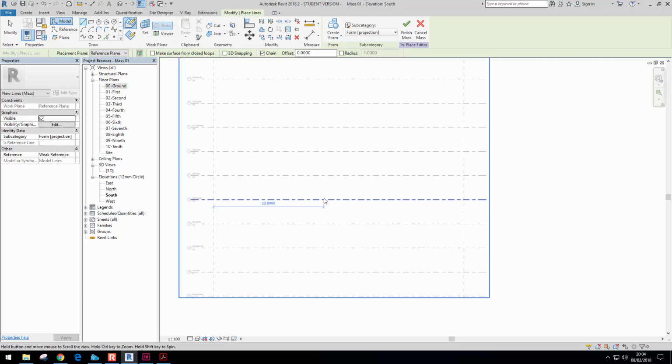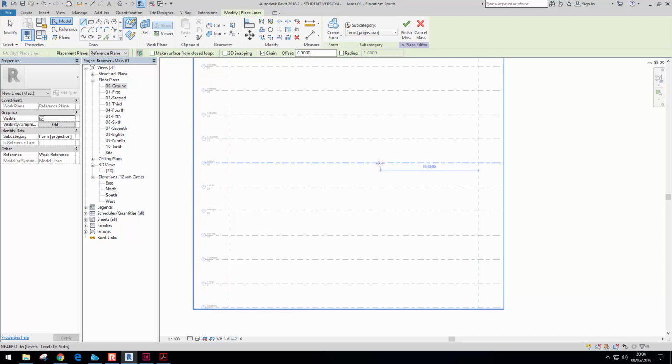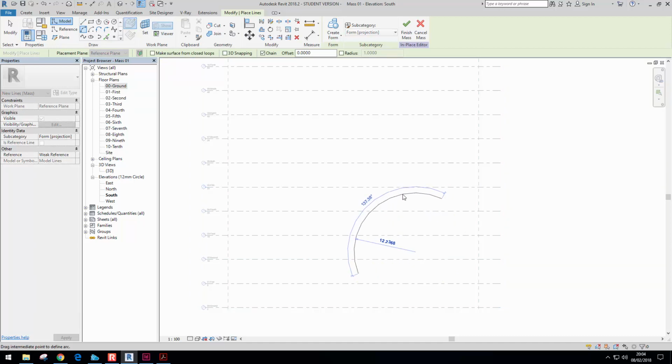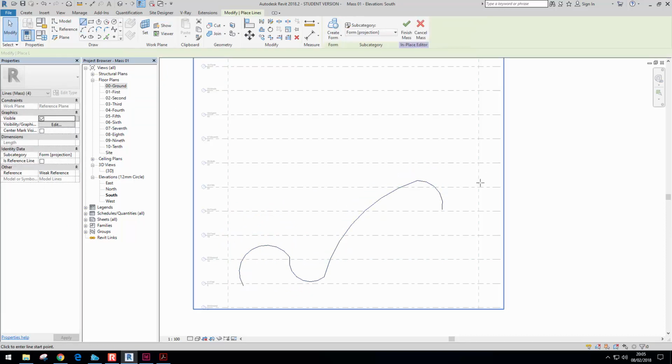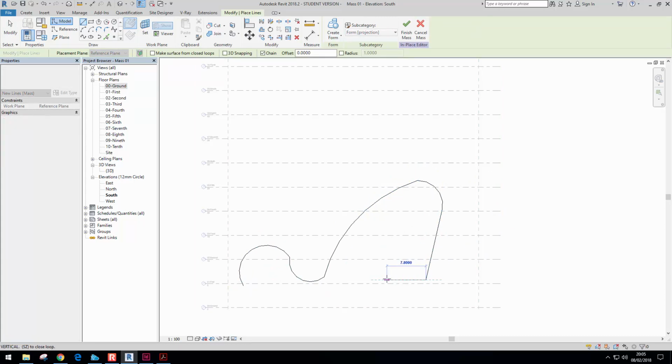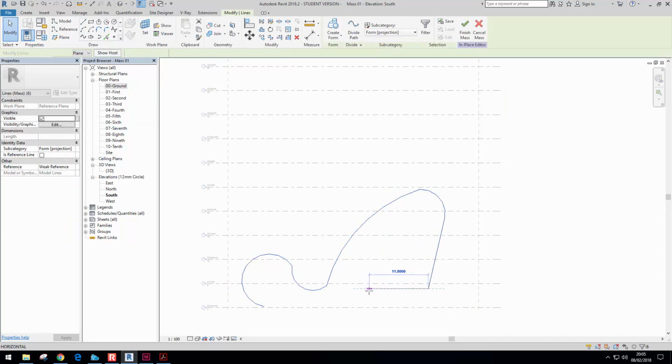So now this is how you can draw your shape. So I'm going to roughly draw that front elevation, so it does something like, so you do a curve here. Try not to use the spline tool because it's not mathematical and might not necessarily work, so try using the arcs, even though the spline tool does give nicer curves, but it might not necessarily work. So just roughly create that form. Click on that again, just pick a line there. So you can take a bit of time to create a form which is a bit more realistic.